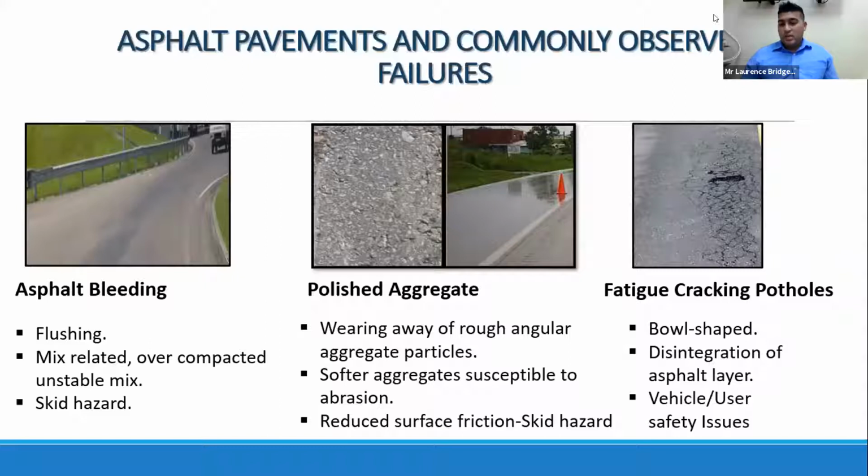Similarly, polished aggregate results in a surface defect as well. This development results from wearing away of rough angular aggregate particles during trafficking, and is a result of softer aggregates, which are more susceptible to abrasion. The result is pavements which reduce surface friction, promoting a skid hazard to the users.